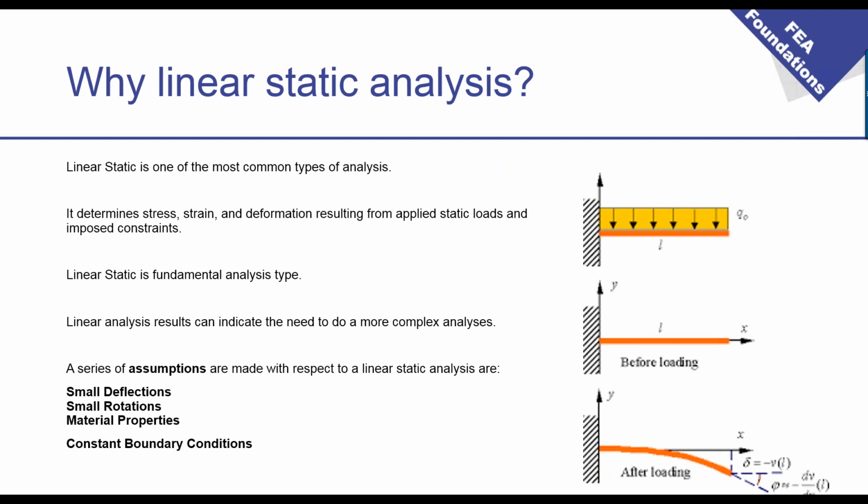So linear analysis can tell you, like I showed you with this factor of safety, that some places on our model have a factor of safety less than 1, which means that the plasticity limit has been reached. This is sometimes a suggestion to go to a more advanced analysis type, like for example nonlinear.